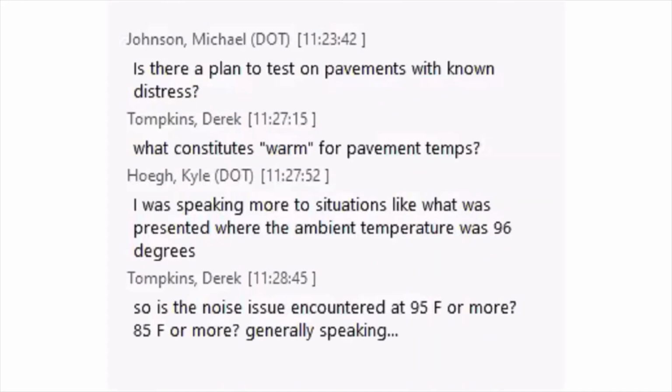I have a comment there also. The shear wave velocity, which we're measuring, is very sensitive to temperature. So I think it will be quite hard to do the measurements when you don't have even temperature, like too early or right after the layering. But yeah, that is yet to be tested.